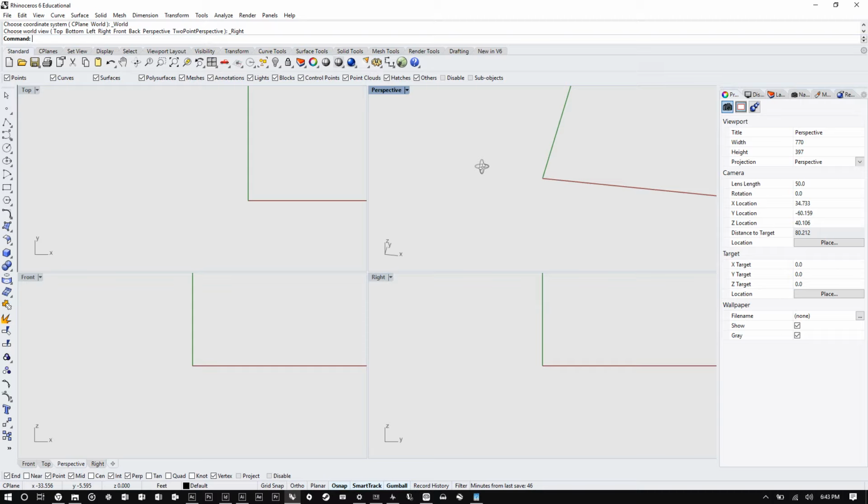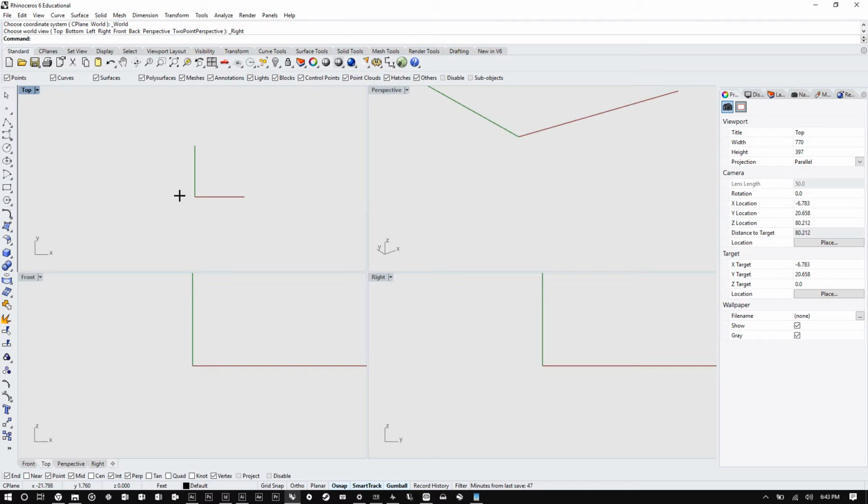Now, overall interface, great question from before. To move around, you want to use the right button. If you click and hold, it allows you to orbit. Shift allows you to pan. The zoom wheel allows you to zoom in and out of all views. The active view is whichever one your mouse is on top of when you use the command.